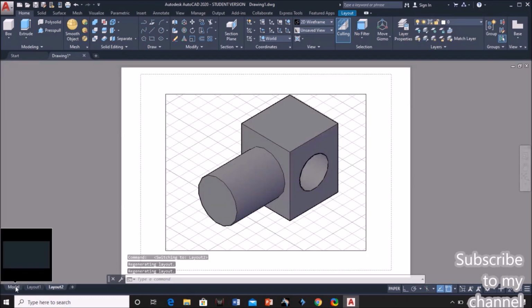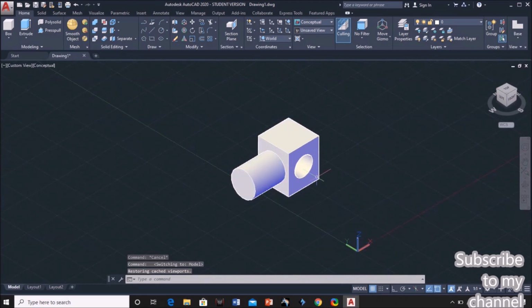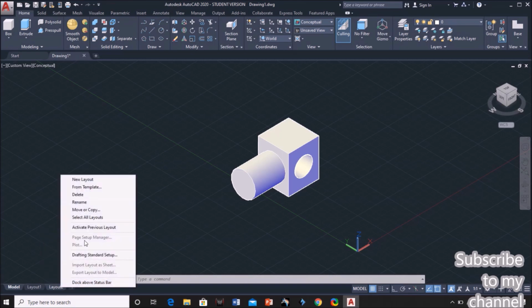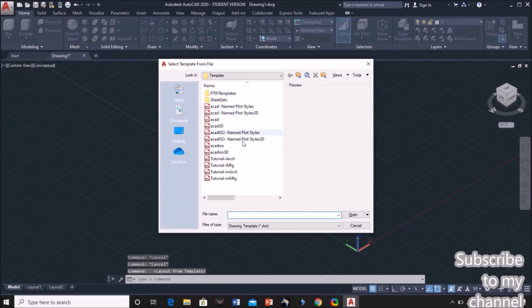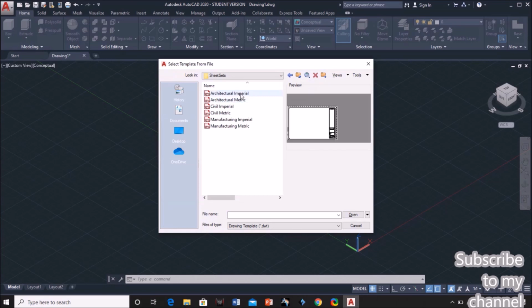Okay, so now I need to get a layout where we get the object in either first angle or third angle. So for that, go to layout, right click and click on from template. Here we will have different types of templates for AutoCAD. Now I'm going to sheet sets. In this we'll have different types, either architectural, civil or mechanical, like manufacturing imperial or metric. Now I'm using manufacturing imperial to get the layout of this figure.